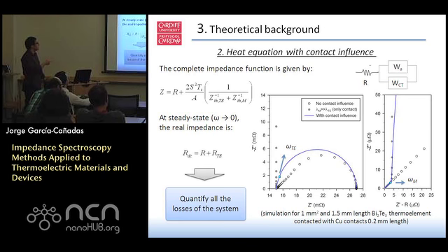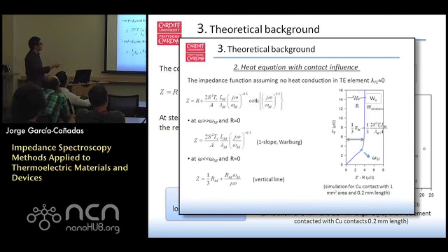And now, from this fitting, it is a little misleading, but the units are very different, because this is milliohm for the thermoelectric and microohm for the metal. If you zoom here to see this response, you need to go to microohms. This is because, if you look at the equation here, the thermal resistance from the metal is given by this equation. The thermal conductivity in the metal is very high, around 400, so this becomes very small.